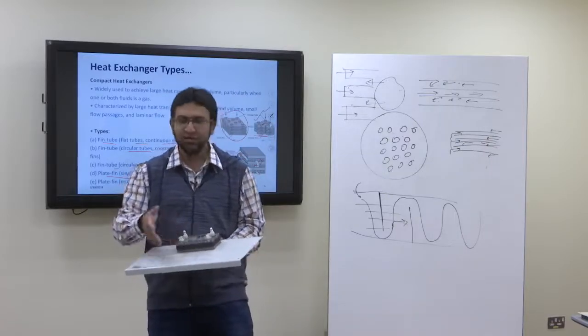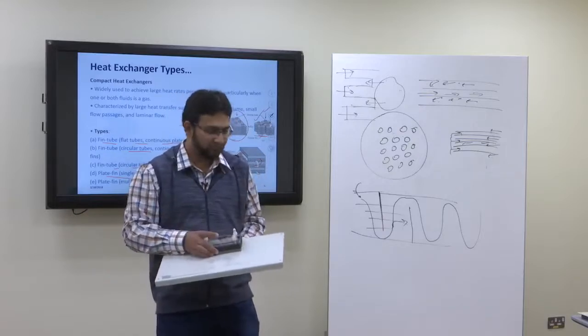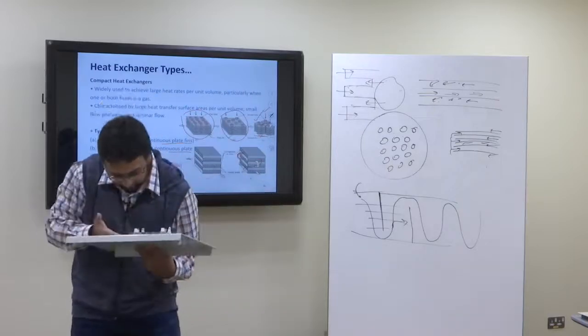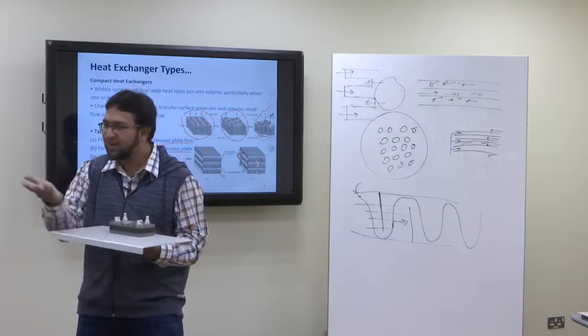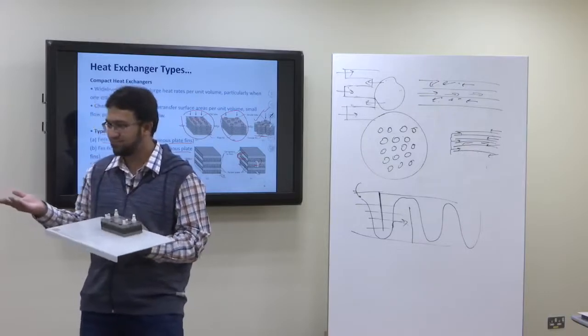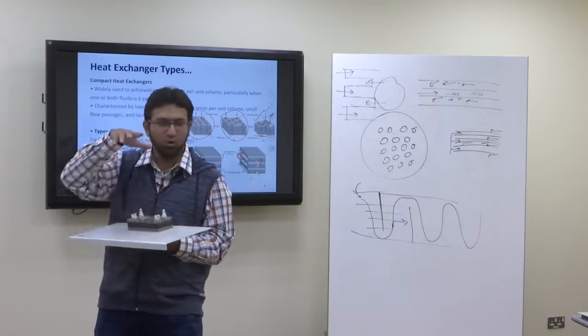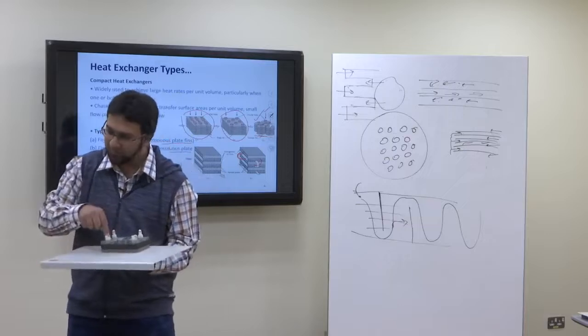So it depends where you are using it. Okay, what is the application? Many things. But if you see here, this is the construction of the plate fin heat exchanger. Plate fin, because all these plates act as fins. Okay, so you have so many plates. They are all brazed together. So one fluid enters from here.